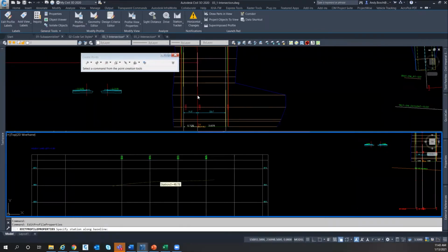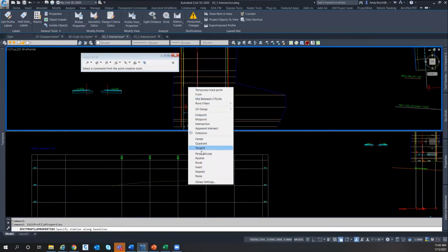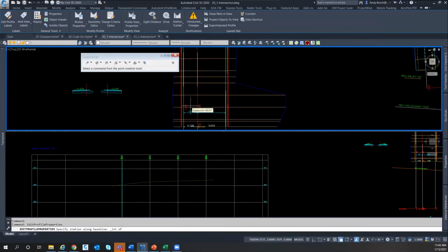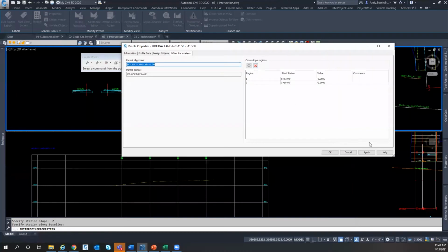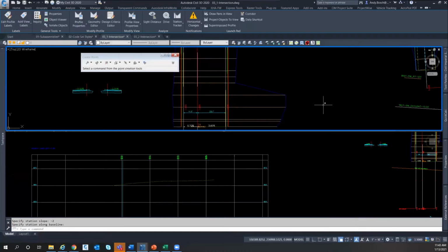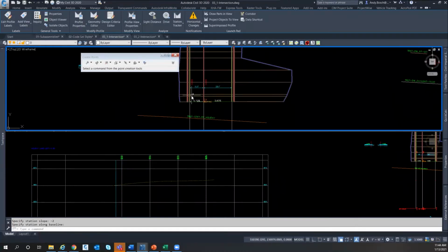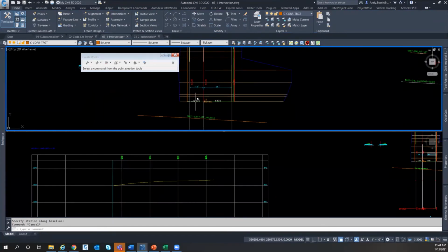And I'm going to add in another transition grade, and I'm going to select this intersection right here, and I'm going to go -2. I hit enter. I don't have to add any more after this. It's just going to assume that's -2 all the way to the end. You could add more transitions in here by just clicking on it here and adding them in. If you pay attention down here, you should see just a slight adjustment made to that. So now I got that transition happening.